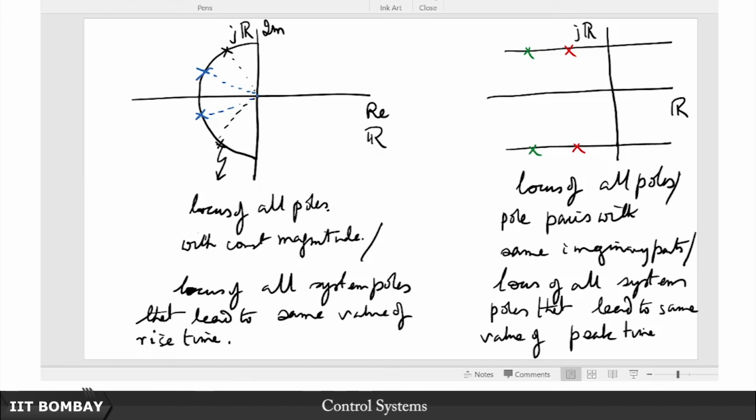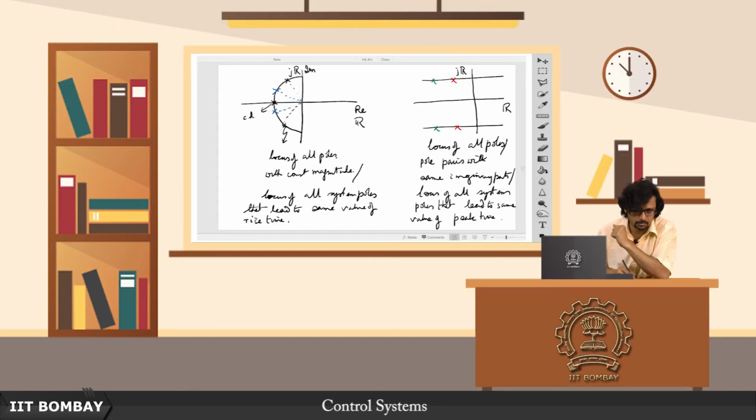Okay. So notice that this rise time is valid not just for an underdamped system but also for overdamped and critically damped systems. Of course, in such cases you will be only confined to this real axis, so you will have poles somewhere here. So this is for, let us say, a critically damped system when you have repeated poles and you then consider this to be the rise time approximately. So I just wanted to put that point as an addendum of sorts.